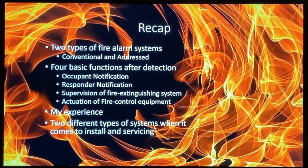All right, I'm going to do a quick recap of what I went over today. Again, there are two types of fire alarm systems that I covered, conventional and addressed systems. What we typically use is the addressed systems, because it's a larger facility that we work with. It's much easier to troubleshoot, fix, and actually reset the initiating device whenever it sets off the alarm. And the four basic functions after detection include occupant notification, responder notification, supervision of fire extinguishing systems, and actuation of fire control equipment.